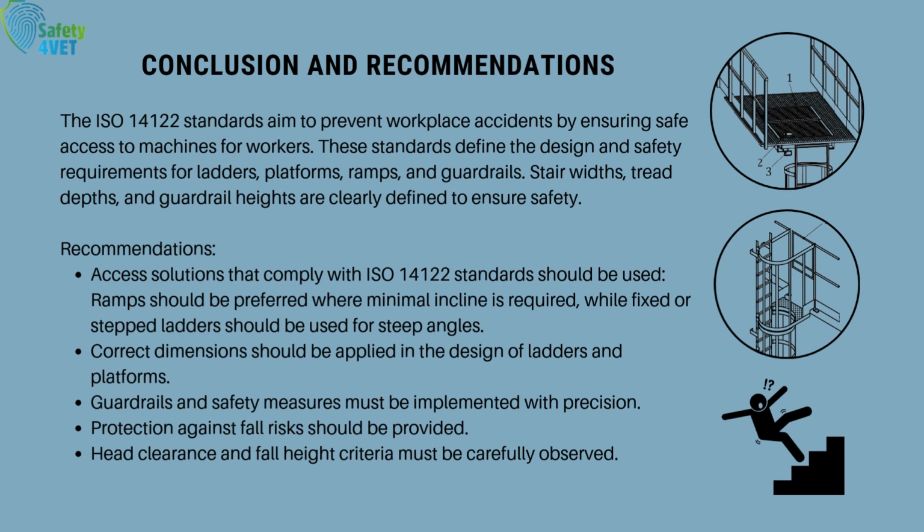According to the ISO 14122 standard, ensuring workers have safe access to machines is vital for preventing workplace accidents. The proper design of access areas should include ramps for low angles and fixed or stepped ladders for steep angles. Stair widths, step heights, and tread depths have been carefully determined to ensure safe access. Guardrails and safety measures must be implemented with precision.